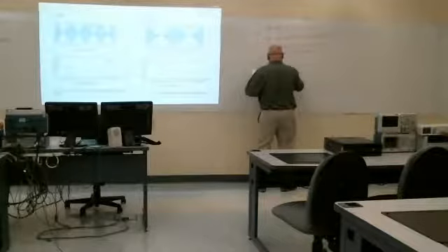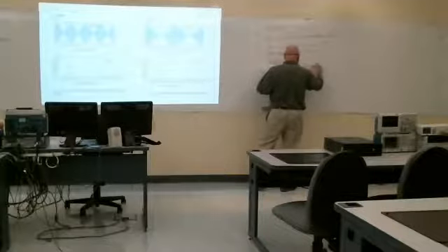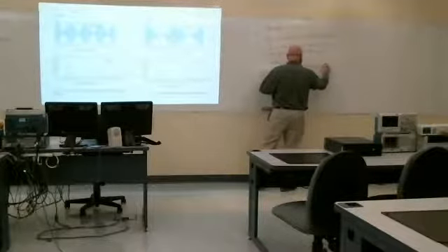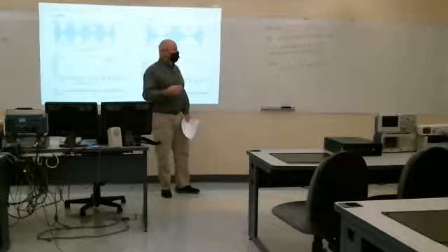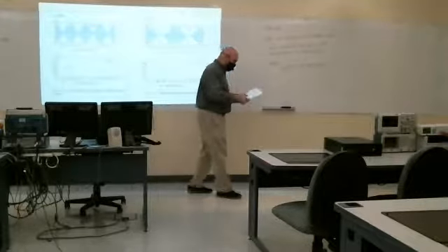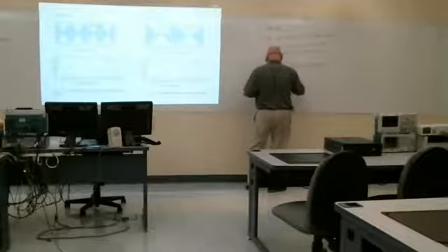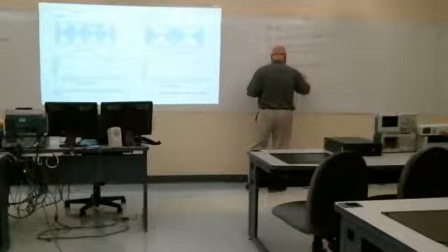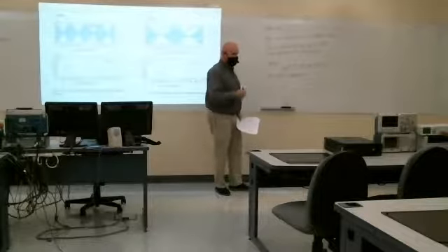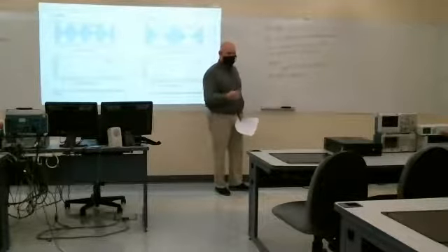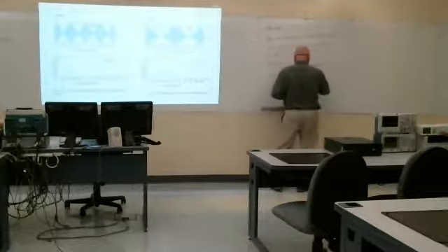All you need to do is multiply by cosine again. So look at this, this is our double sideband signal. It would work with AM, it works with FM, it works with television. This technique is used throughout modern communications. Okay, but to shift the spectrum, so here it would be centered around F1. Take our low pass signal multiplied by a carrier that's operating at a frequency F1. It translates the spectrum up around F1.